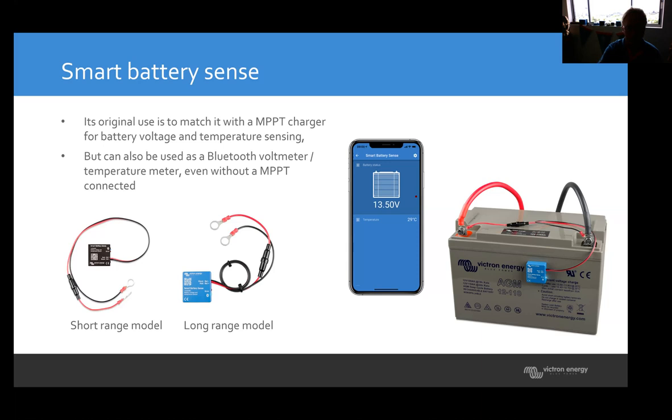Because generally in the bow or the keel of the boat, it's a fairly cold point, and that's where your engine room is at start. So if you have say around 25 degrees in general, especially here in Queensland, and all of a sudden you jump on board and one battery's sitting at 35 degrees, it's also a detection that there's something wrong, maybe a bad connection or poor wiring or something's going wrong. So yeah, handy little device for the sake of a few bucks. It's not very expensive and can fault find very quickly.